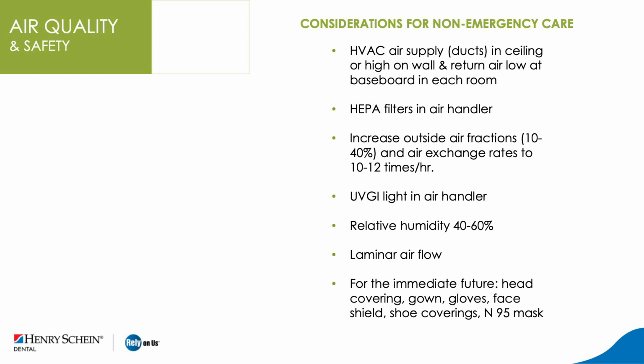And also, one element that we have not addressed yet is just the airflow itself. We want to try and create a laminar airflow. And if you tell that to a mechanical engineer, they understand exactly what we're talking about. What that is, we are minimizing the turbulence of the air as it comes out of the air handler. It comes out as if you can just think of a smooth sheet with no wrinkles in it at all, or water that comes out of a faucet and it looks like a clear ribbon.